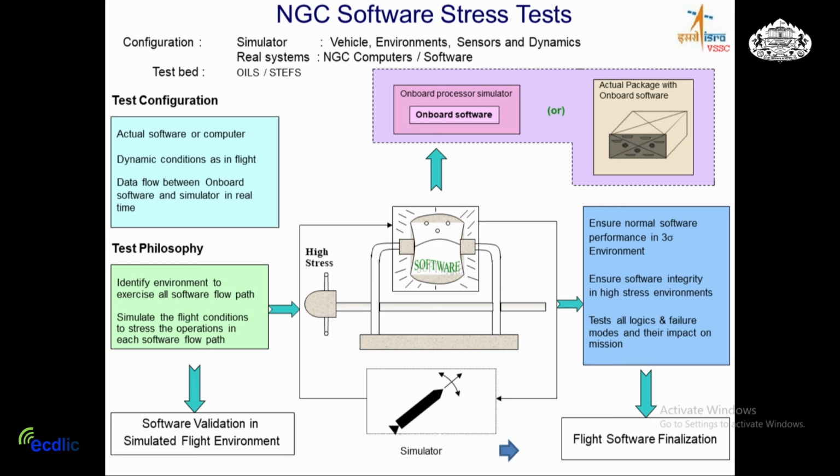Disturbances are provided to the onboard software, not just in a plus minus 3 sigma sort of environment where winds and propulsion, everything varies within tolerable defined limits. It goes to unexpected disturbance. Supposing there is a failure, in which case you will not be able to restrict your disturbances to only plus minus 3 sigma.